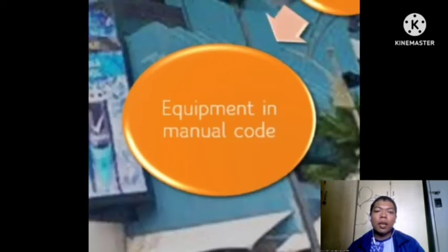The fourth is equipment in manual mode. Some of these building operators are not entirely comfortable with the new technology and are overwhelmed with the complication of the initial setup of the BAS. We have found the building operators will simply prefer to run the equipment in manual mode instead of fixing the glitch or programming error in the BAS. Running equipment in manual mode can waste a lot of energy, and might keep the equipment on after hours.